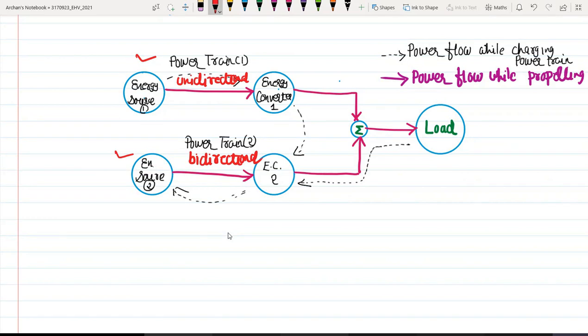Operating each powertrain in its optimal efficiency region is essential for the overall efficiency of the vehicle. Say if I talk about the IC engine, the IC engine generally has its best efficiency operating region with a wide throttle opening. But operating away from this region will cause the efficiency to suffer a lot. On the other hand, efficiency suffering in an electric motor is not as detrimental when compared to an IC engine that operates away from its optimal region.